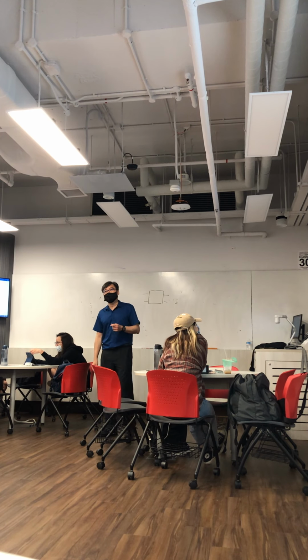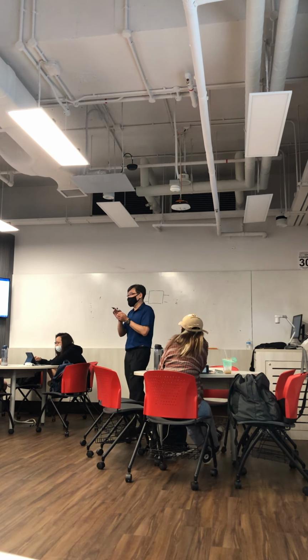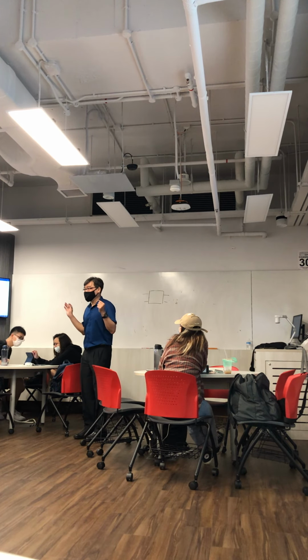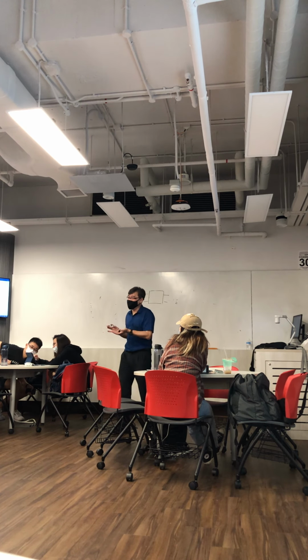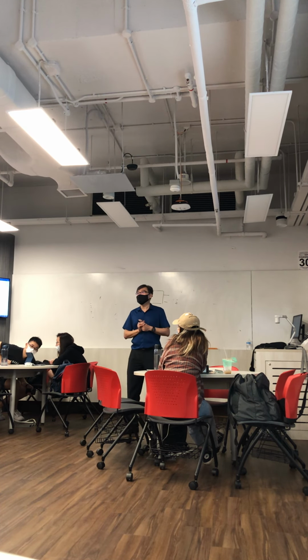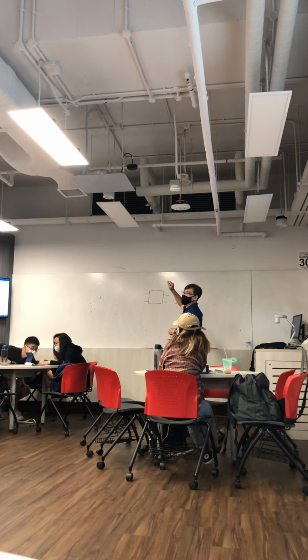What do you mean by linear time invariant? It means that the characteristic of this system doesn't change with time, so it's time invariant. If it keeps changing with time, it is very difficult to characterize. Linear means that you can apply superposition. The relationship is not squared and all those things. That is not linear.